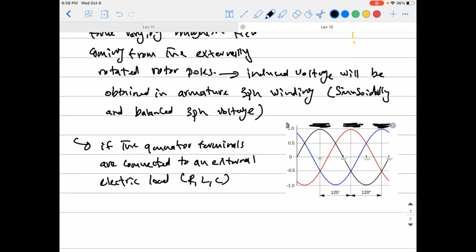If you remember, in the DC machine, when we used a load on the generator terminals, it was just resistive, because for DC power all the loads are seen as resistive, if you remember from your circuit courses. But if you're talking about AC, you can have any kind of loads and you can feed power to any kind of loads, R, L, and C.